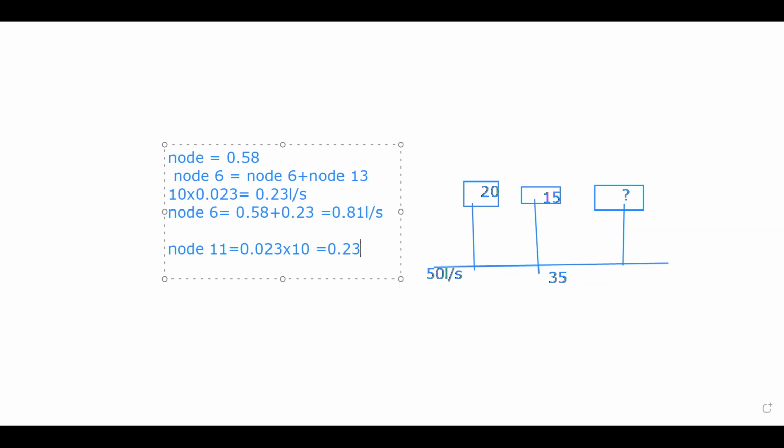So this one will have minimal pipe. I can make my minimum pipe 2 inches, 50 mm. So any pipe that is less than 1 liter per second, or less than 0.58, I will just use nominal size. I will call it nominal design, nominal pipe. I'll just use nominal pipe to make the design faster and easier for me.